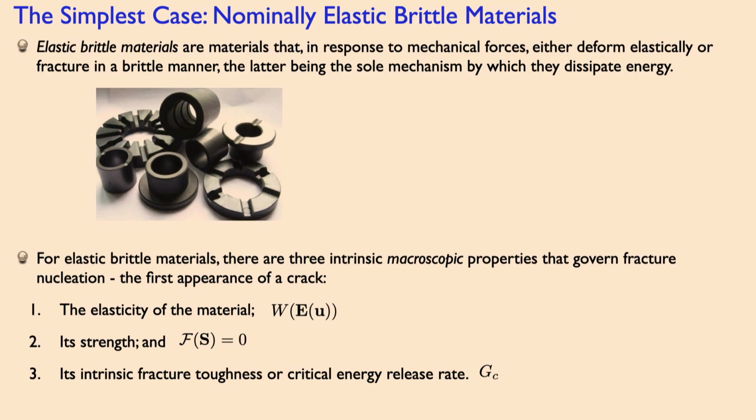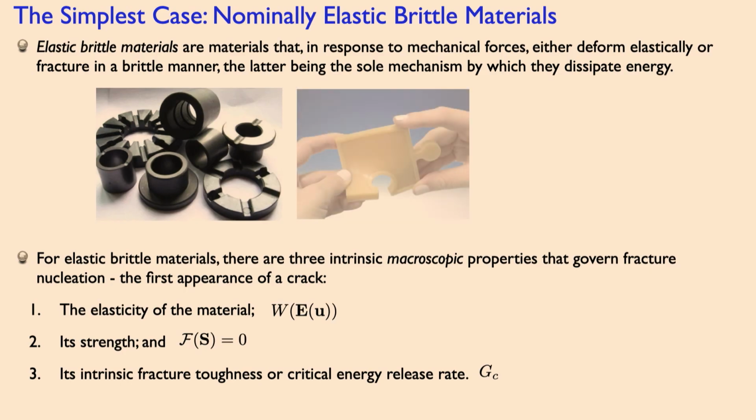And so when we think about materials that qualify, many of us would think first about hard ceramics. So this is an example of graphite components. But this definition actually applies even more so to soft materials. So this is a polyurethane elastomer. And once again, this is a very good assumption for how this material responds. It does one of 2 things. It deforms or it breaks very suddenly, when you put enough forces on it.